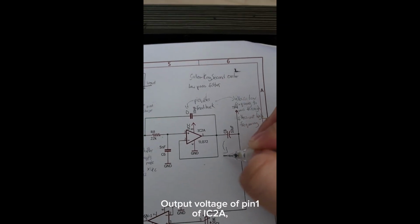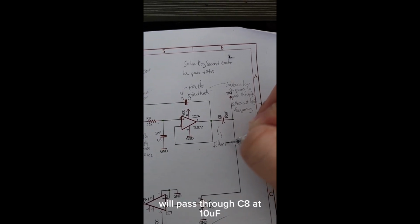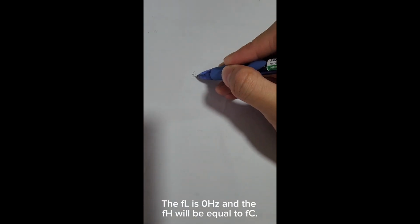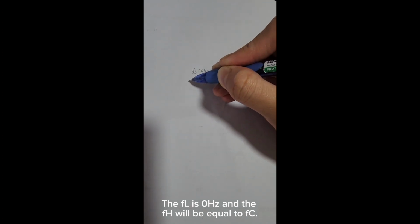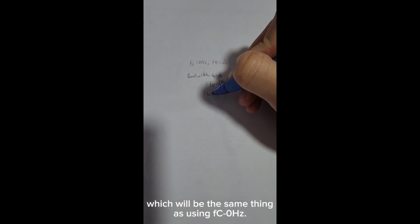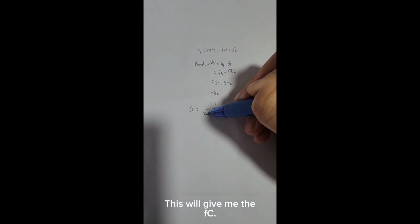The output voltage of pin 1 of IC2A will pass through C8 at 10 microfarads to filter out any DC signals, acting as a coupling capacitor. The low frequency will be 0 Hz, and the high frequency will be equal to the cutoff frequency. To find the bandwidth, we'll use the high frequency minus the low frequency, which is the same as using the cutoff frequency minus 0 Hz. This will give me the cutoff frequency.